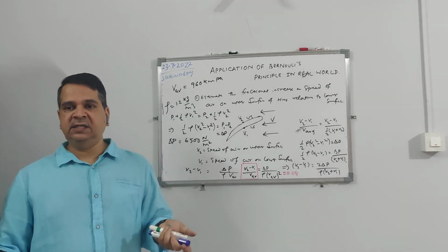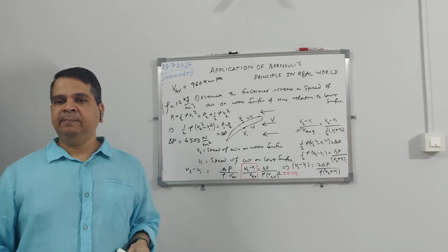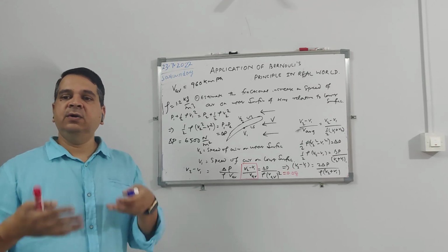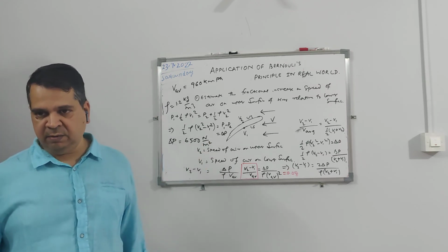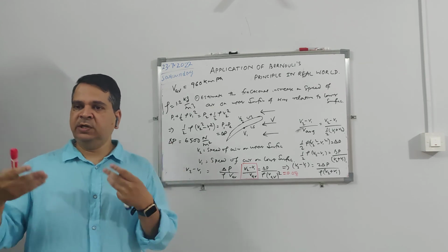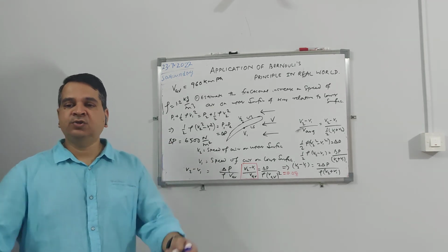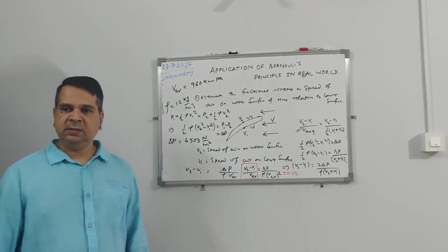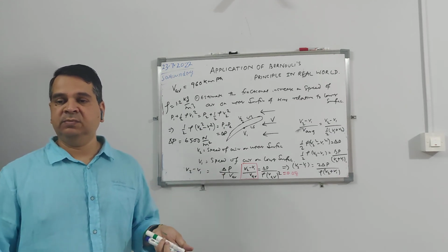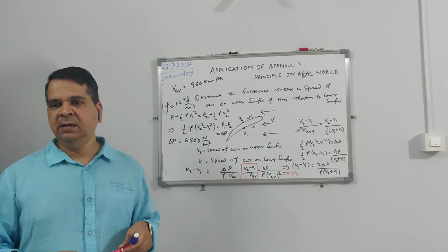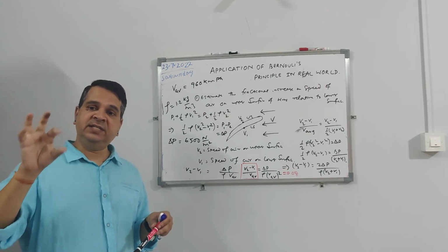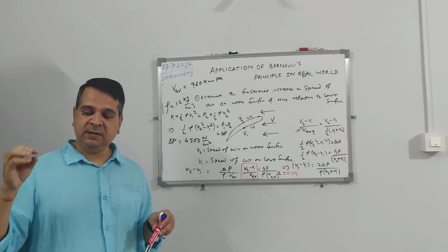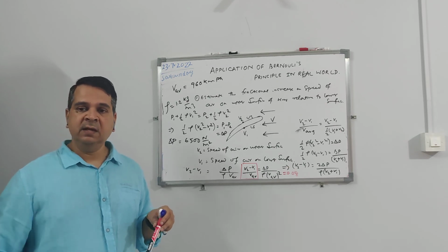So when a designer designs an aircraft, he will know the weight of the aircraft, and corresponding to weight, what the lift should be. Once he knows the lift, he will have an idea that this airfoil can provide an 8% increase in velocity. If there is an 8% increase in velocity, what should be my wing area? That a designer needs to calculate. That's how in aerospace engineering they do the conceptual design, then preliminary design and detail design. But you can see the physics behind it is the driving force. Engineers put numbers, but there is physics behind it. It's all from Bernoulli's principle.